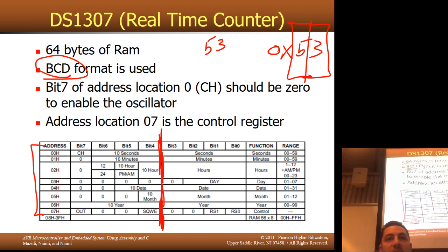Now, you had to deal with splitting nibbles up, second lab, right? So you know how to split nibbles up. In later labs, you had to divide by 10 and divide by 100 and so forth. We did that in something. I know I went through that with somebody. That was the most recent lab, to display the number? Yeah. So that was harder because you had to do division. This does not require any division. It just involves splitting up nibbles. It's one of the advantages of BCD. So since you have to display the time on a clock, it's good that this is all BCD. So, things that we need to know here.